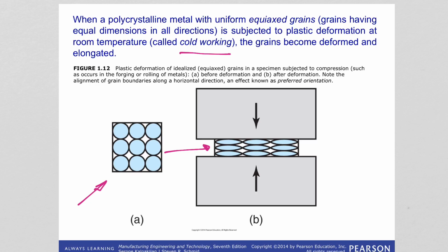Of course the strength increase will depend on how much strain the material is subjected to, how much you deform the material, because the higher the deformation, the stronger the metal will become. Okay, and basically you are also increasing the number of dislocations, right? And this way strengthening the material due to the reasons we just described.